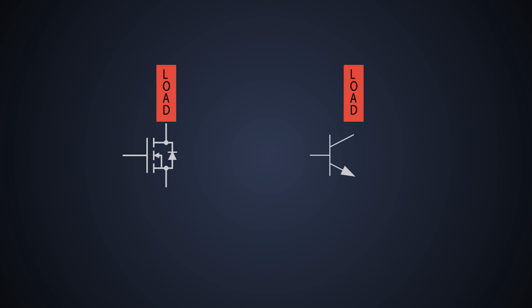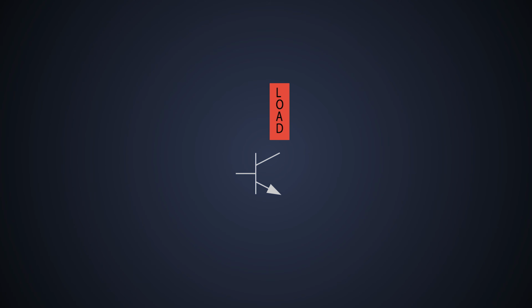A transistor can provide a regulated supply of current. We can use BJT or MOSFET depending upon the current and voltage requirement. So we can add a load to the transistor. We can bias a BJT at its base and a MOSFET at its gate. For now, we'll consider a BJT.